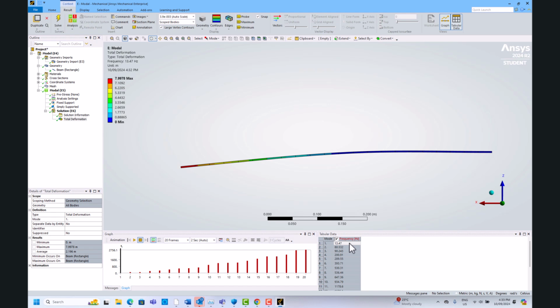Yes, why is that? Well, I mean, just where you've got support and maybe the fixed end is exactly different. Yeah, exactly. When you have a fixed end, in FEA we have an ideal fixed end, but in reality we usually cannot achieve that. Even if you have a clamp and very, very firm, you will still have stiffness at that point. And when you have some sort of stiffness, especially when you deal with a vibration of metal, then that can have this type of 5 or 10% sort of difference.